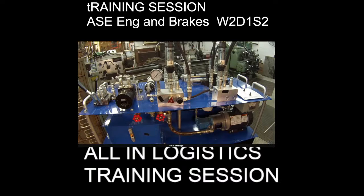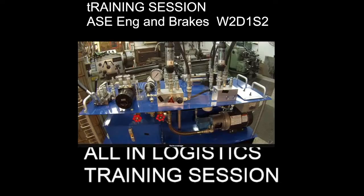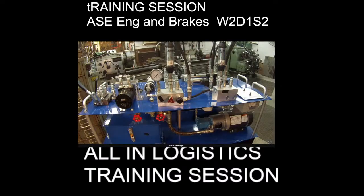So those are the essential components of any hydraulic system in order for it to function. Alright, the definition of hydraulics is a means of transmitting power by pushing on a confined fluid. As you can see by these hoses and the way all this stuff is hooked up right here, that fluid has to be confined to be able to do work. Whether it's pushing this cylinder out right here or rotating this hydraulic motor right here, that fluid is confined in all these hoses right here.